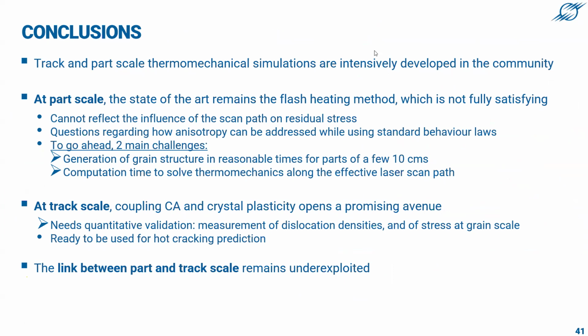So I think we agree that in the community, track and part scale thermomechanical simulation are really intensively developed. At part scale, the state of the art remains the flash heating method, which is not fully satisfying. Not fully satisfying because, in fact, it cannot reflect the influence of the scan path on the residual stress.